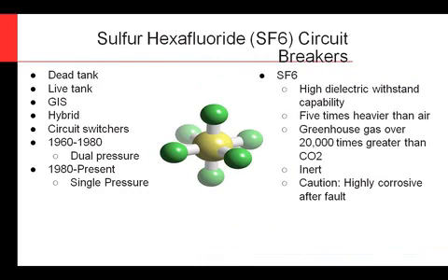So the next thing I'll talk about is SF6 style circuit breakers, sulfur hexafluoride. These can come in dead tank, live tank, GIS, hybrid, circuit switchers. The original design from about the 60s to the 80s was a dual pressure design, and then after 1980 and on, they came out with this single pressure kind of auto puffer style design. So SF6, sulfur hexafluoride, it's a very nice dielectric. It has a very large withstand capability.